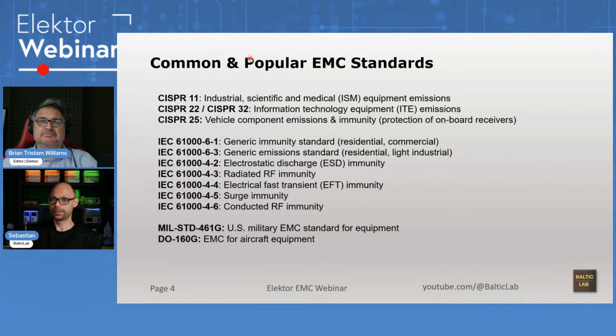Here's a few common and popular EMC standards, and this is really just a few. There's hundreds of them. I'm probably giving an understatement with hundreds. The most common one is the CISPR 11 Industrial Scientific Medical equipment emission standard. Then CISPR 22 doesn't exist anymore, but is often mentioned in the literature. It's been replaced by CISPR 32. Most of the devices that you're watching this webinar on are tested against CISPR 32, like your laptop, your desktop PC, and that sort of stuff.